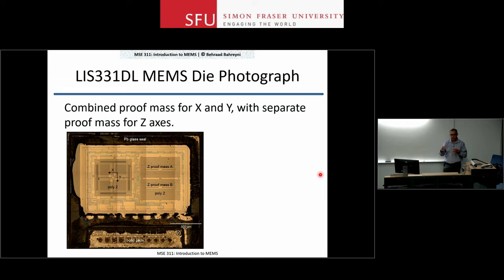At the end of the story, you really cannot make that system to be insensitive. So if you have an acceleration in X, your electrodes in Y may also pick up something because of this cross-axis sensitivity that you may bring out, or may make worse by the design of these compliance mechanisms on your structure.